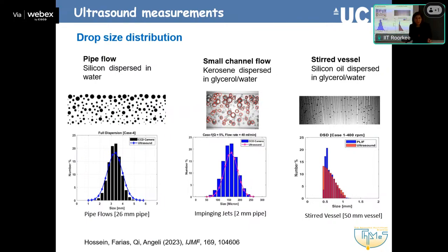You cannot do PIV in a plant. Okay, you do it in the lab. But if you want to have this quick information, then you need instruments like ultrasound, pressure transducers to the same job, thermocouples, because you can connect them online, you can read information straight away. And that's why it has some use in that case.